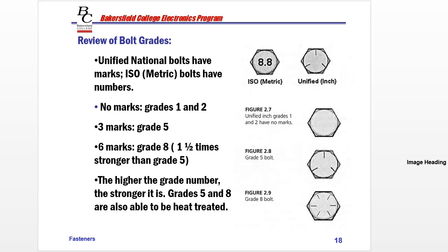One of your greatest resources is the telephone. Call the manufacturer when you're having a problem like breaking bolts. Talk to them about it. See what they recommend. Make sure you're putting the correct bolt back in that machine. It's very important.